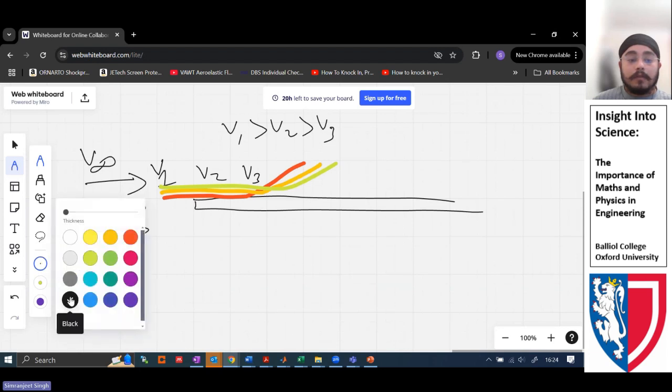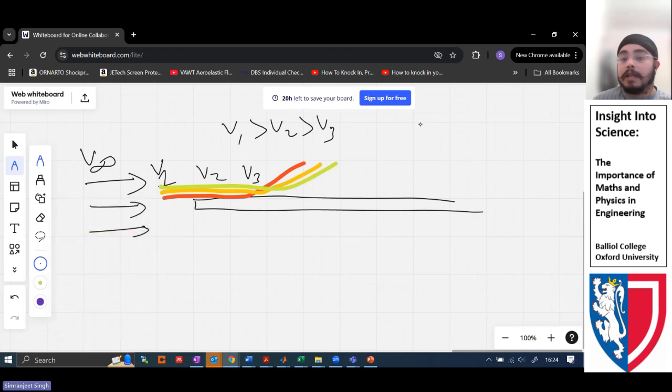The expression that we can deal with in order to calculate the drag comes down as D equals 1 over 2 rho V squared A Cd. Here, rho is the density of air, V is the velocity, A is the area of cross section, and Cd is the coefficient of drag. Let's suppose we are replicating this scenario from the real world in our simulation, that being our assumption could be